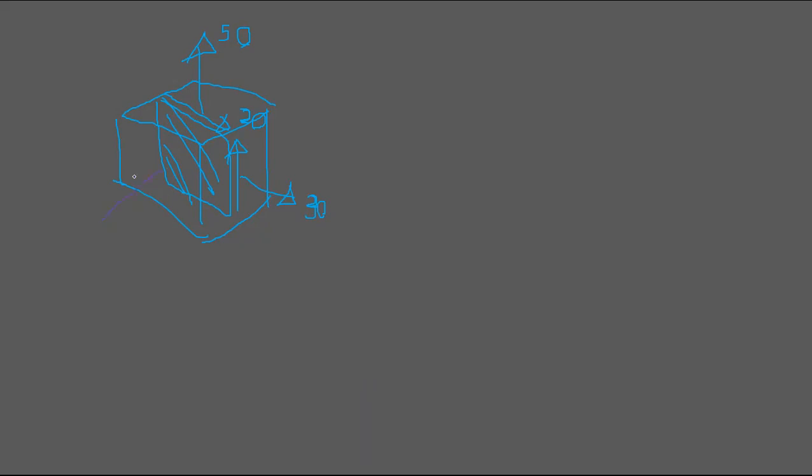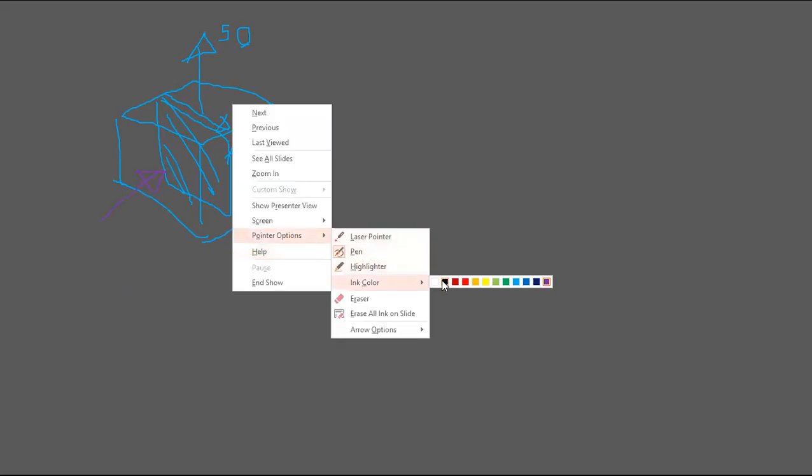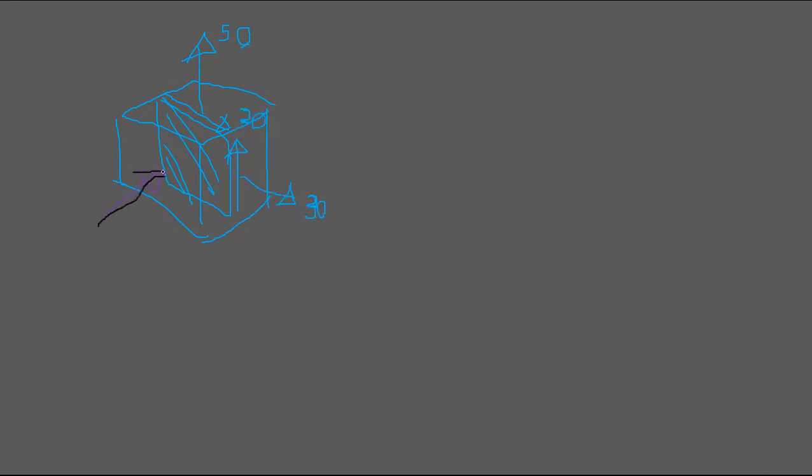On that face you will only have compression, right? No shear stresses, so that means it directly becomes the principal stress, right, of minus 40, sorry, 40. That's anyway minus. Okay, so you can draw this Mohr circle still, right? It's 30, 20. 20 is anti-clockwise shear. Let's say 30 is here, 20 is here. This is 50 and clockwise shear, that's positive. So these two are the points you can plot.